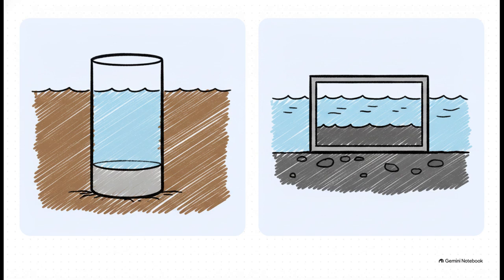Open caissons are designed to actively penetrate the soil. As the earth is excavated from the inside, the caisson slowly sinks. Once it reaches its final design depth, engineers place a massive, thick concrete seal right at the bottom, directly in the water. Floating caissons, on the other hand, are totally different. Because they have a closed bottom, they don't penetrate the soil at all. Instead, they just rest flat on a hard, level surface. Because of this, their load-carrying capacity relies 100% on base resistance since there's zero friction along the sides from the soil to help hold them up.